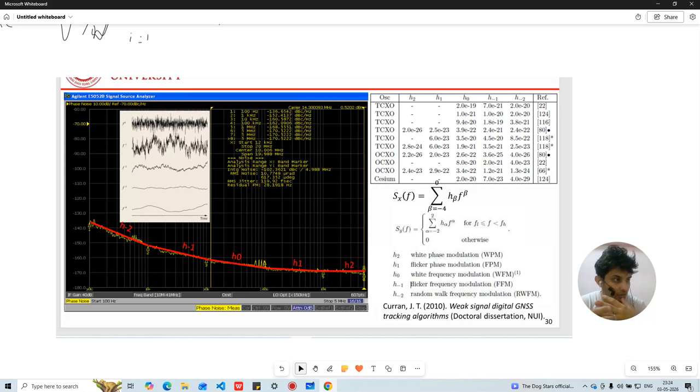This is actually a really good slide, basically showing the full story of oscillation in one picture. Let me break it down. The big picture you're looking at is phase noise, the source's frequency offset from a carrier. The x-axis is how far you are from the carrier, and the y-axis is the noise level. The red line is the important part. It shows how noise behaves in different regions.